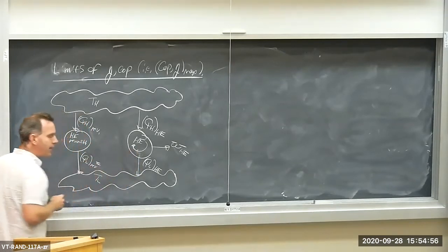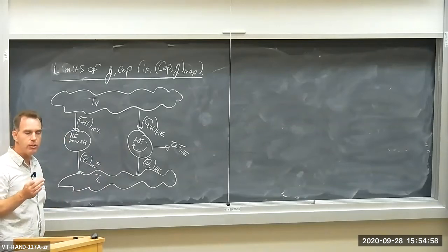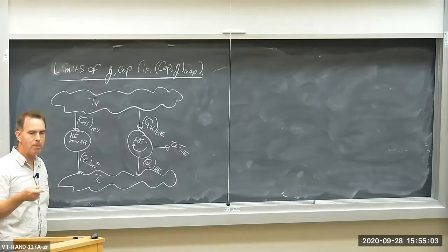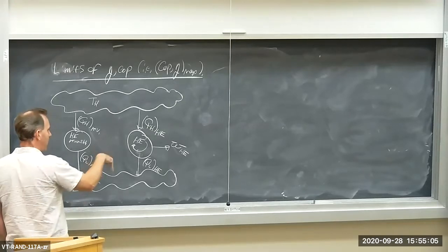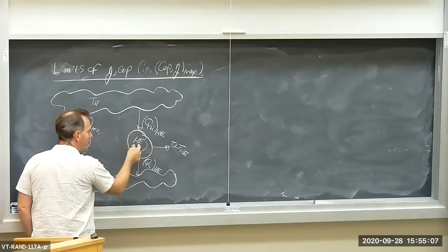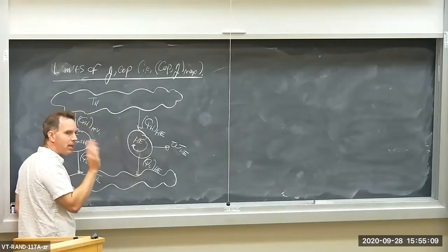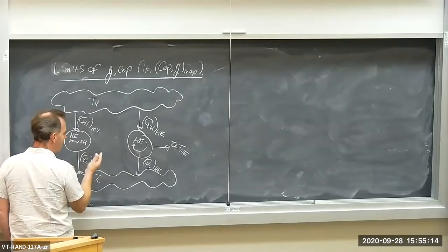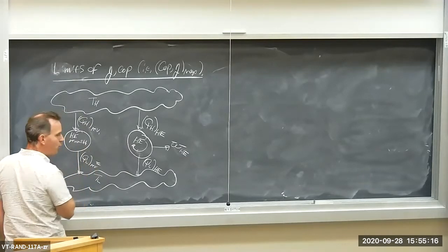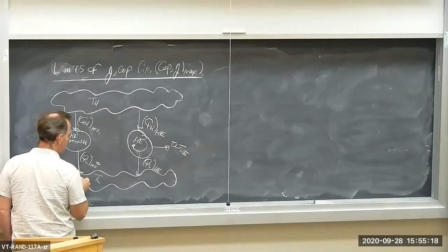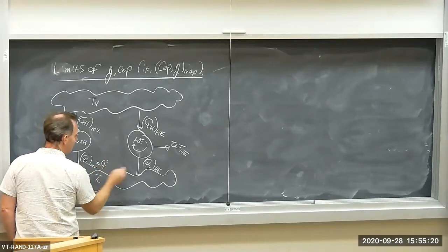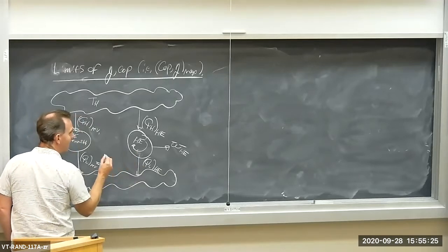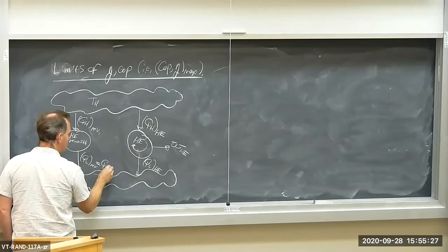And this regular heat engine may or may not contain irreversible processes, friction, unrestrained expansion, heat transfer across a finite temperature difference. I have not said that this is reversible. It's just a plain heat engine. But this guy is reversible, and I've made it big or small so that the heat rejected to the low temperature reservoir is exactly equal to that being rejected by our regular non-reversible heat engine.